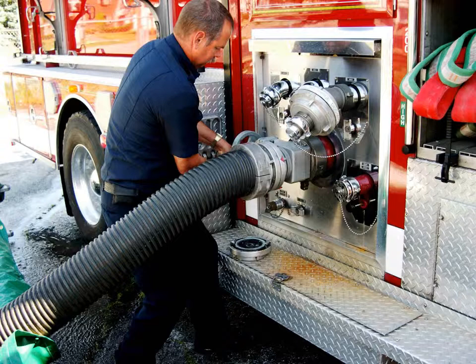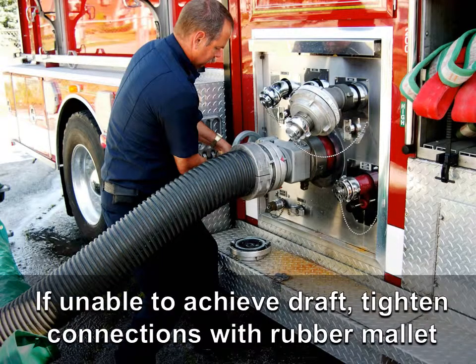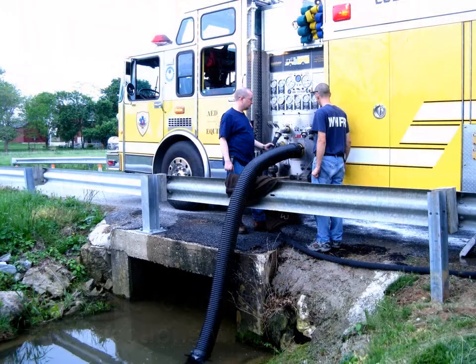If you're unable to achieve a draft, tighten connections with a rubber mallet. If still unable to draft, the lift may be too great for the pumper to overcome.